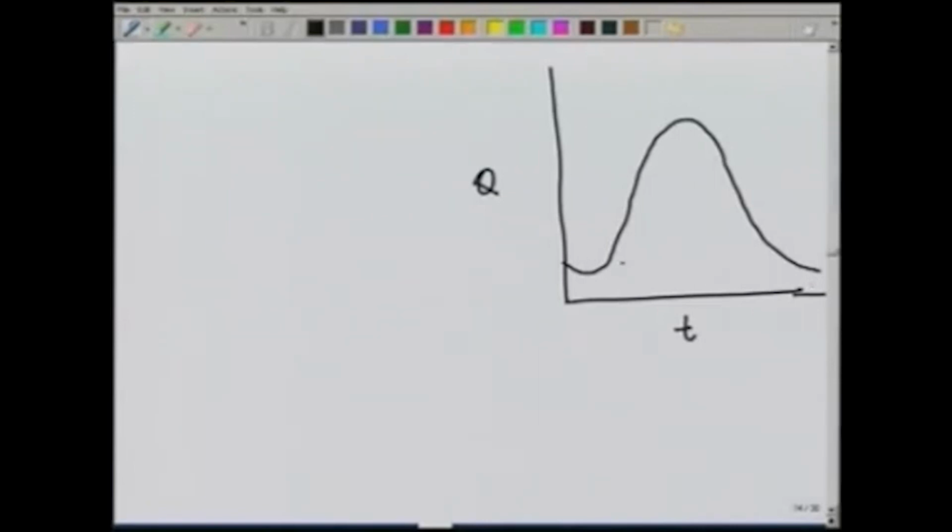So, if you look at this typical hydrograph, the rain has started, and it is conventional to show the rain on the hydrograph itself. The rain hydrograph is shown on the hydrograph itself to tell that this hydrograph is because of this rain. Now, if you see from this figure, the flow in the river is decreasing even after the starting of rainfall.